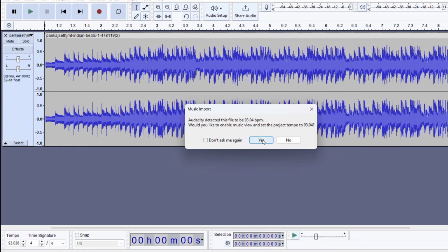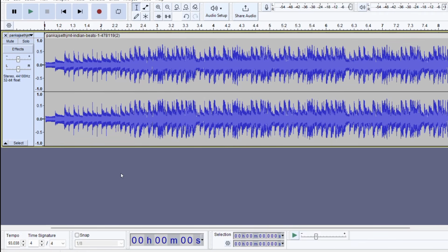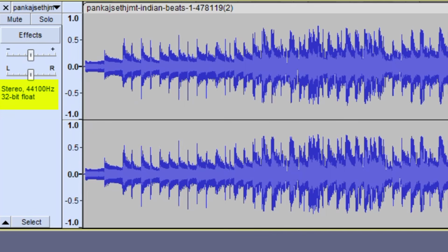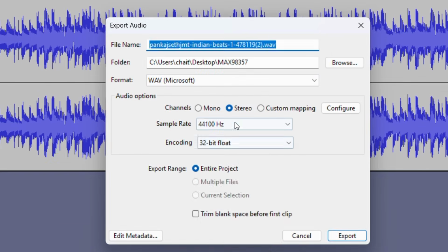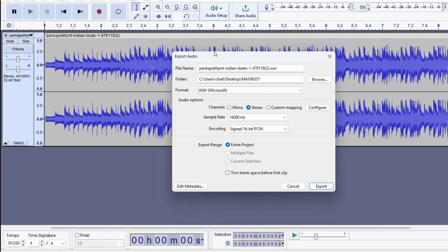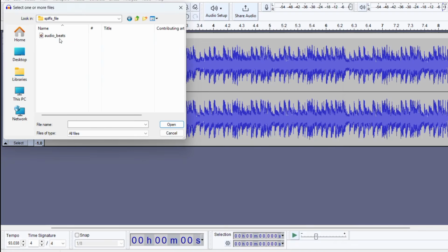Alright, that's enough with the code. Now it's time for some hands-on. Let me first show you the wave audio file that we will be storing in flash and playing back. The original file was in stereo with a 44.1 kHz sample rate and 32-bit resolution. I have simply downsampled it to 16 kHz and reduced the bit depth to 16 bits. After that, I made sure the file size stays within 1 megabyte.